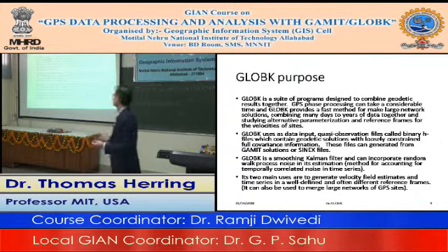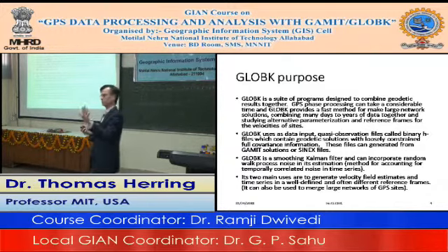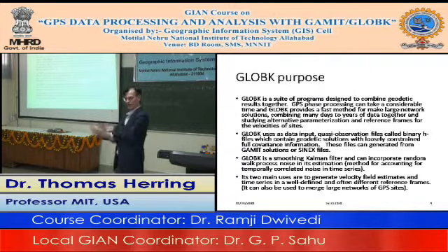So it's that speed up by manipulating the covariance matrix and the solution vector rather than going back to the original phase observation. For those of you who have done estimation, it's essentially a sequential estimation technique. You're adding a new estimation on top of the covariance matrix that you already have.